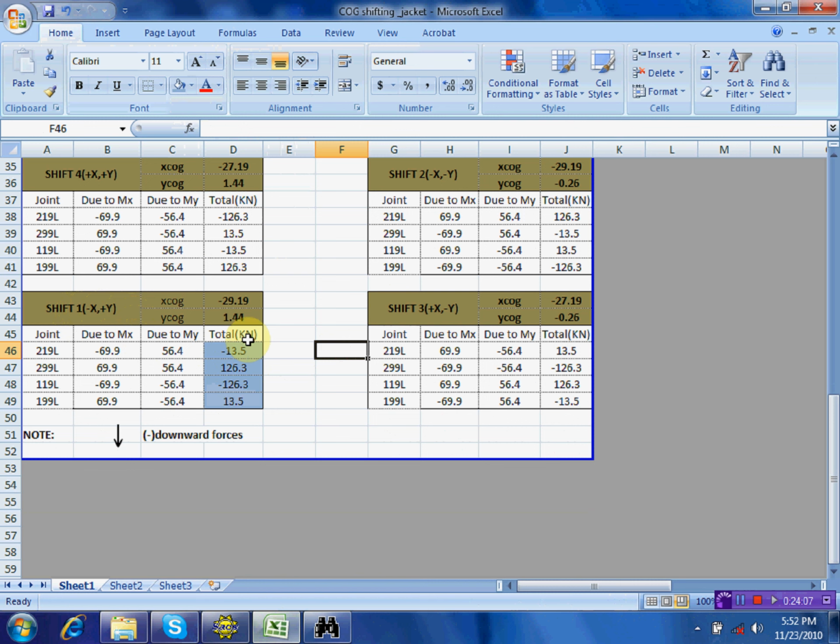Okay, for example, this is my original COG. This is the X axis, this is Y. We are looking at the plan. We want to shift the COG minus X. So this is delta X minus and positive Y, right? So delta X actually has a value of 1, and this one is 0.85. So this is now your new hook point. That's the new hook point, right?